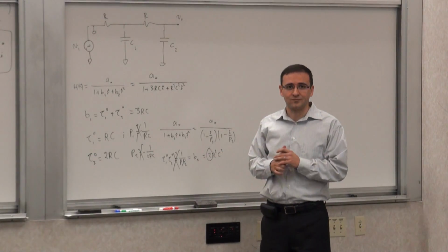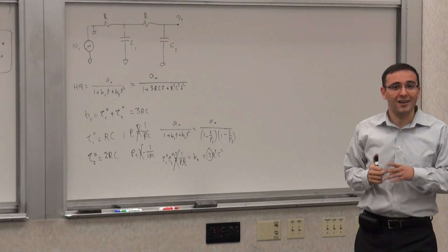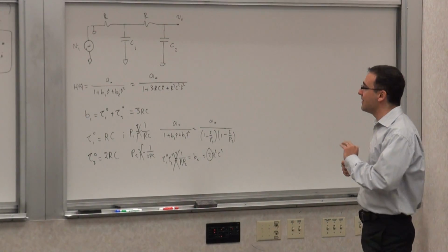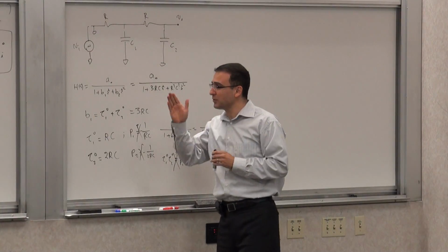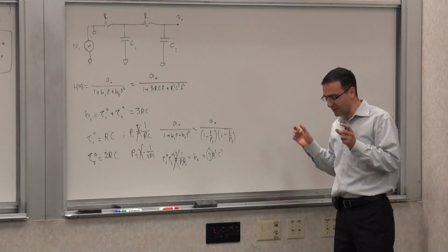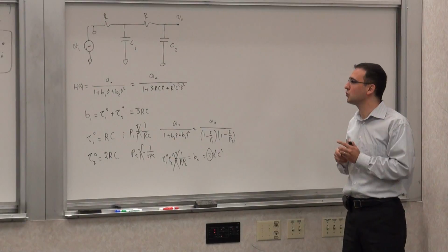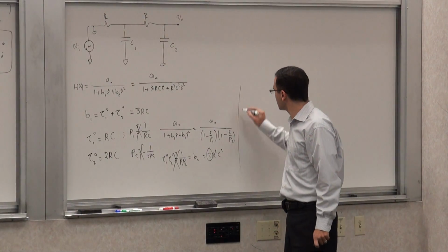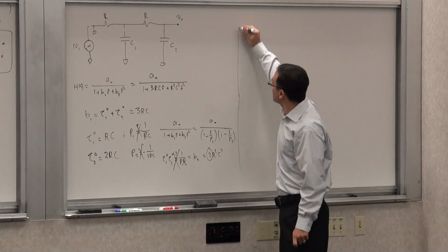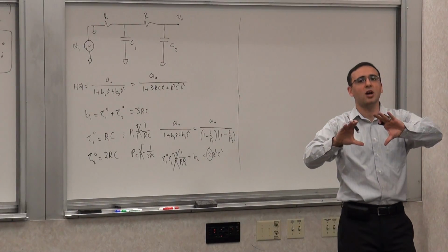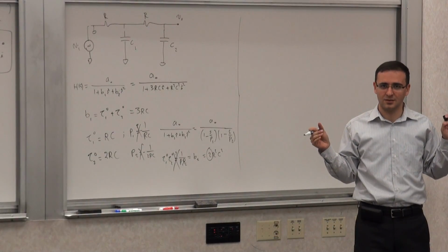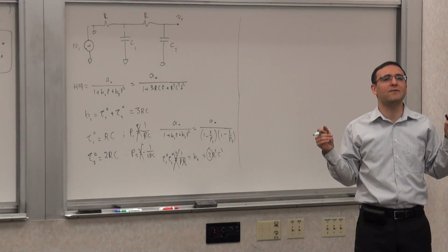So what is true? Now, I said unless. I had an unless in my discussion. What was my unless? I said that individual separation of a time constant may be true under certain circumstances. Now, what are those circumstances? I said that if a time constant is uncoupled from the rest of the circuit, then it can be factored out.